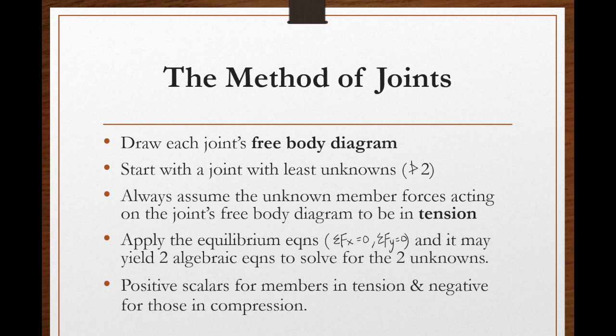Apply the equilibrium equations, the summation Fx and summation Fy equal to 0. This may yield two algebraic equations that can be solved for the two unknowns. The solution gives positive scalars for members in tension and negative for those in compression.